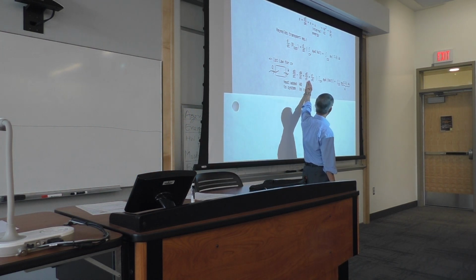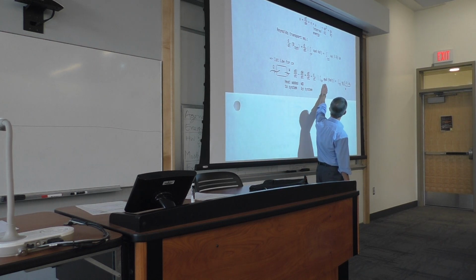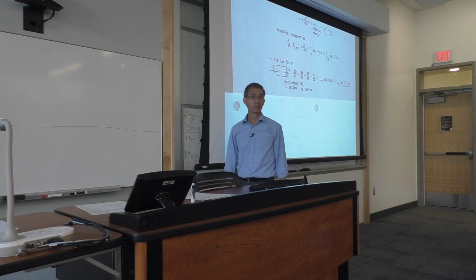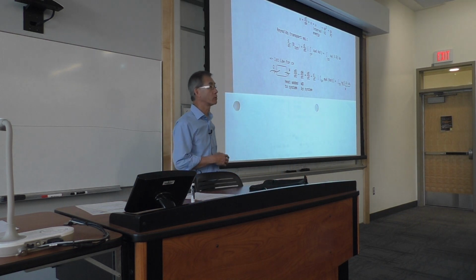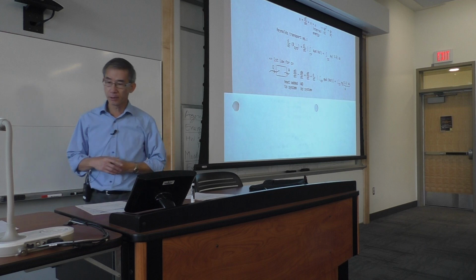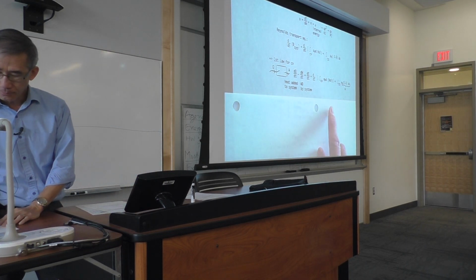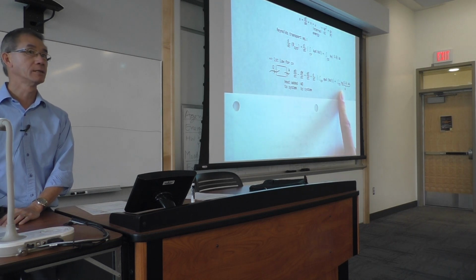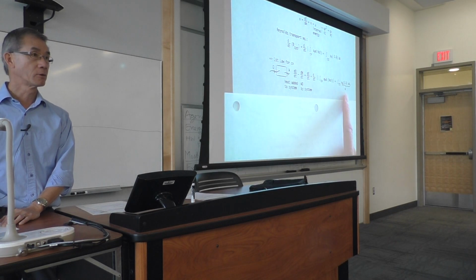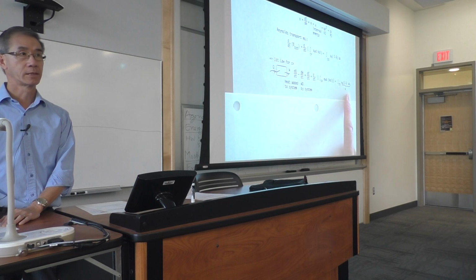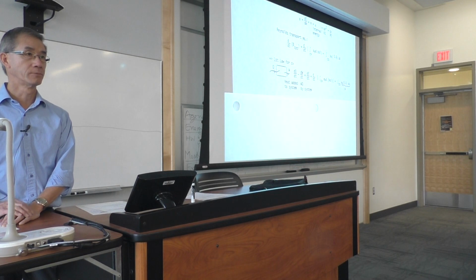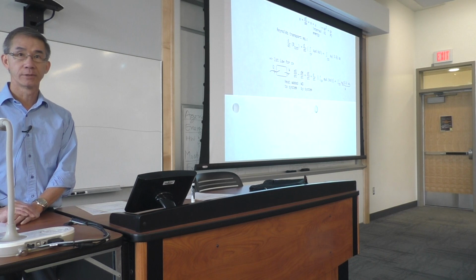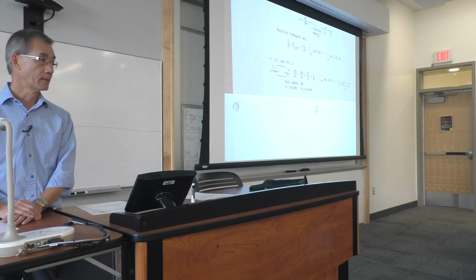The transport equation of Reynolds allows me to relate that to the fluxes of energy: the term inside my control volume, the rate of change with respect to time, which is this first term, and the energy fluxes leaving and entering my control surfaces. Just like continuity and just like momentum, it reads the same, except now it's switched to energy. Any question on that? Does that make sense to you? Okay?